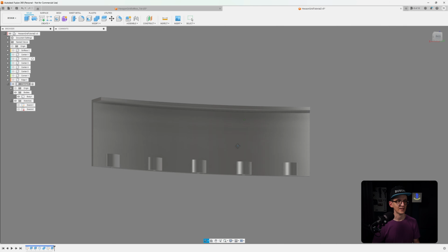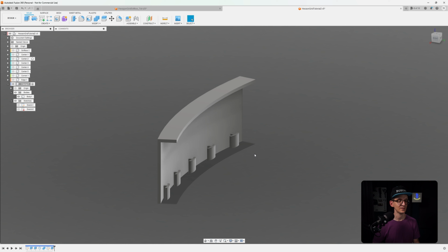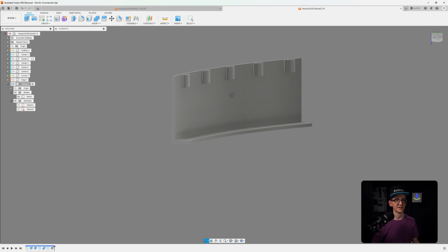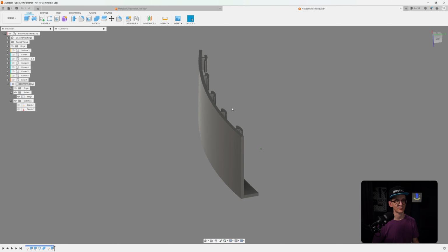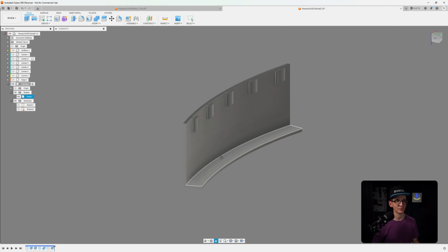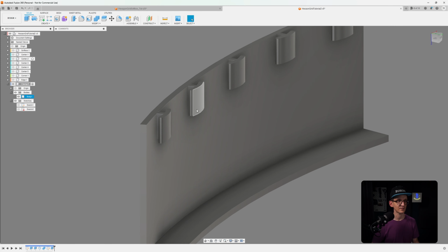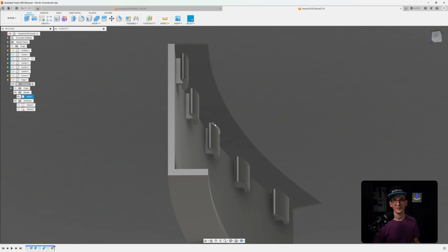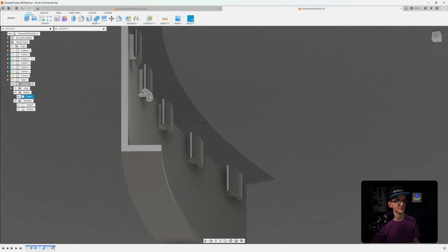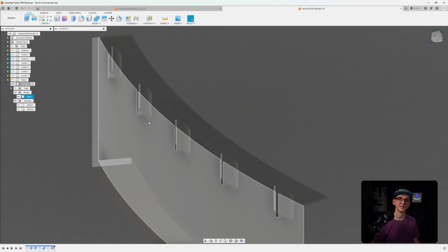Now, as the Prusa Mini is an FDM printer, it is important to make sure and to keep in mind that whatever you're creating is actually printable, which is a problem with this piece, at least to some extent. So due to the curvature, I would say it's impossible to print it this face lying down, because that will turn out really ugly. So I would like to print it in a standing position like this. And then those will hang in midair. But with the new tree support, which I also did a short video about, and their awesomeness, which you can find here, is that you can then easily paint support positions here, and then let the tree support do its magic. And I think that will work out great, actually.